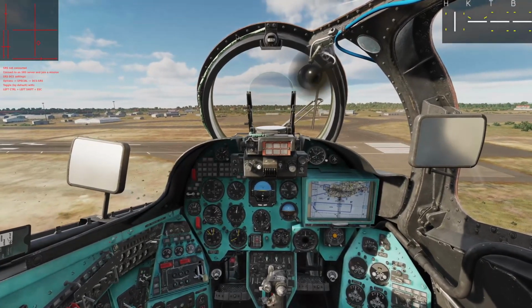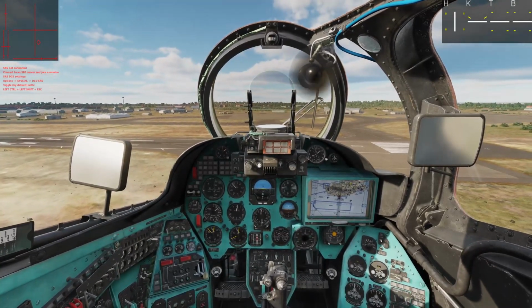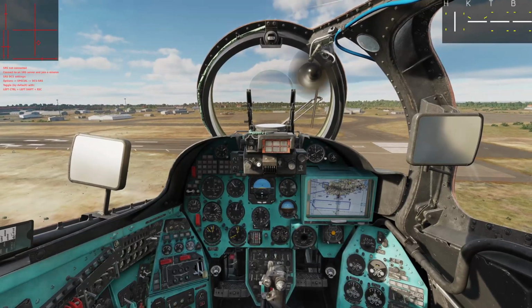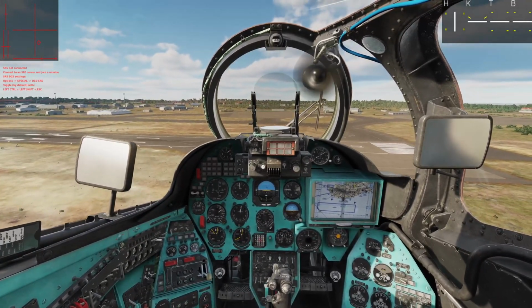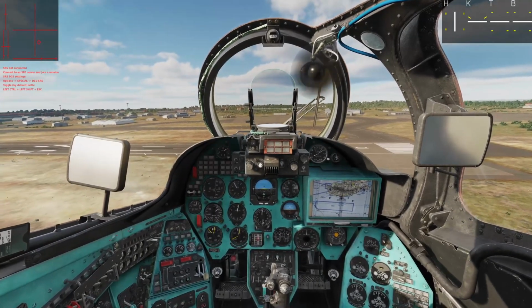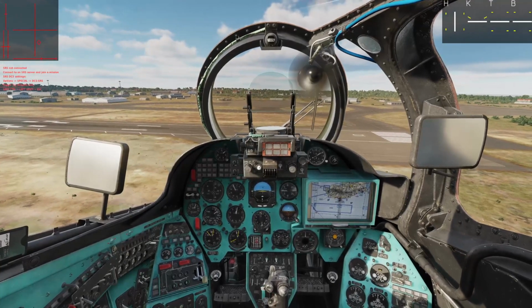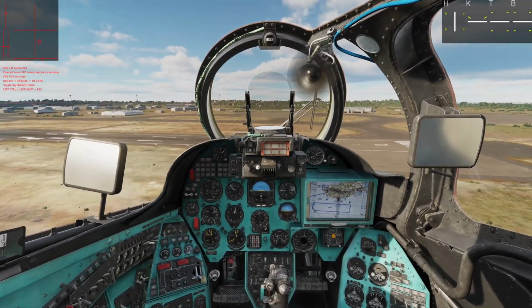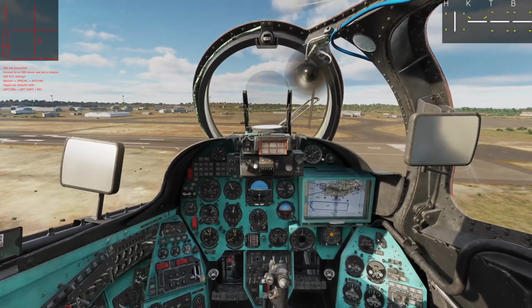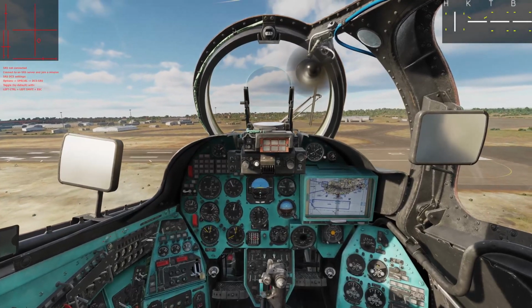And this is because the aircraft is going to want to weather vane into the wind, and that's for two reasons. One, air is hitting the vertical tail, and that's going to want to swing the aircraft around to face the direction of travel. Additionally, the tail rotor, because it's entering a climb condition, the power required is going to increase, and the inflow, I should say, is going to increase into the rotor.